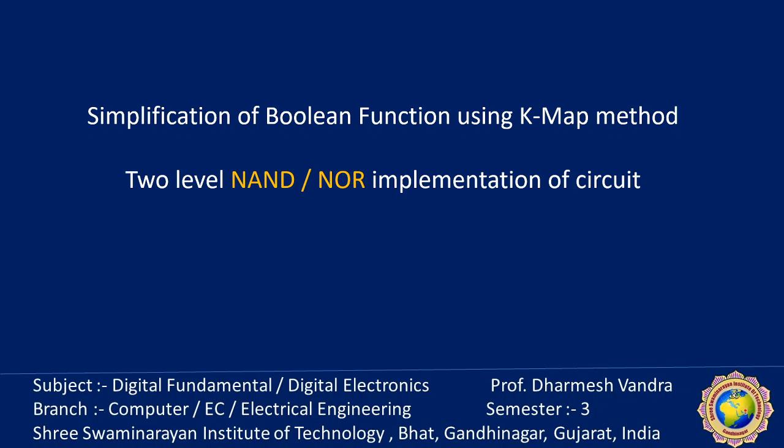Digital circuits are more frequently constructed with the NAND or NOR gate than with AND and OR gates. The first reason is that the NAND and NOR gates are easier to fabricate with electronic components and are the basic gates used in all IC digital logic families.